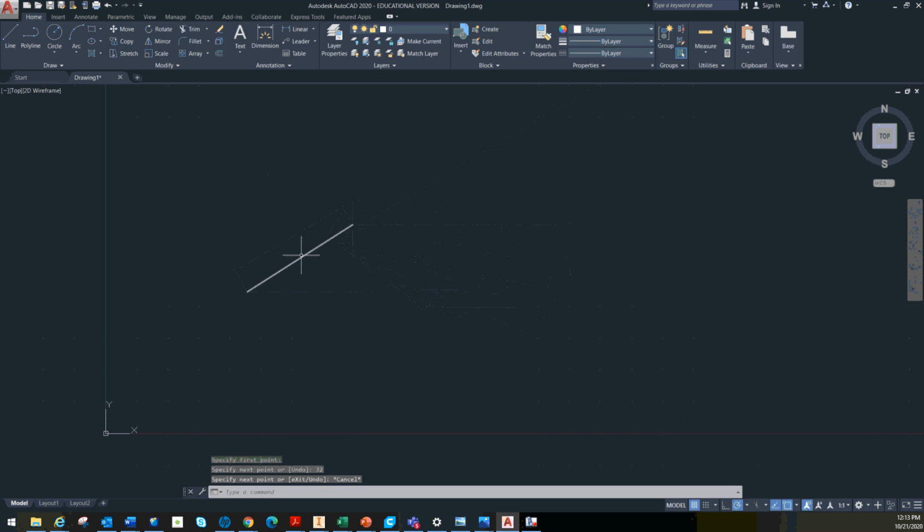Okay, that's our line tool. You can specify length and angle. Now, once you select a line, you're going to see that it turns blue and you get a box on each end. You can now size this line up by grabbing onto a box and pulling it and stretching it. So it does change those properties that we initially put in, but it allows you to quickly maybe extend a line to a certain point or shorten it a little bit if you need it to meet up with another line. It's a quick way of doing that. Okay. All right, I'm going to delete that line, and we're going to look at a couple other things.